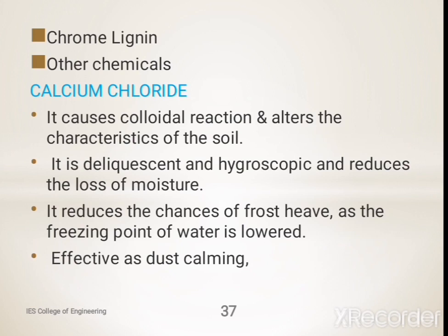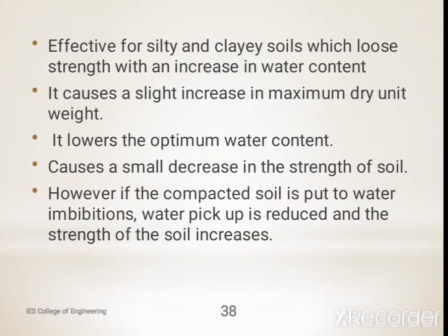It causes colloidal reaction and alters the characteristics of the soil. It is deliquescent and hygroscopic and reduces the loss of moisture. It reduces the chances of frost heave as the freezing point of water is lowered. Effective as dust palliative. Effective for silty and clay soils which lose strength with an increase in water content.